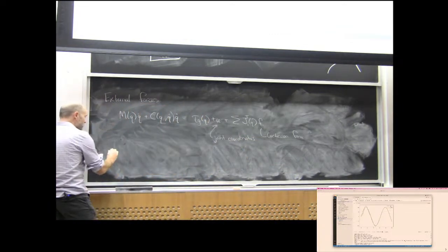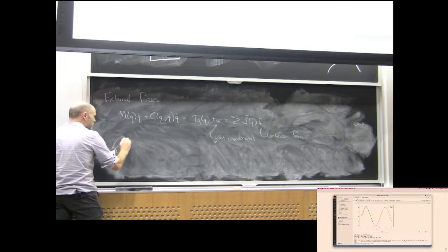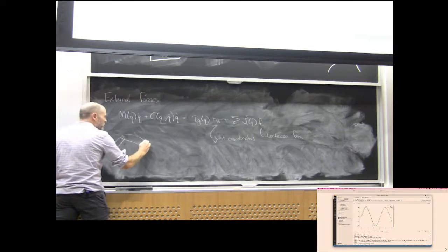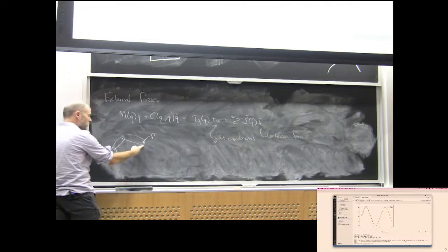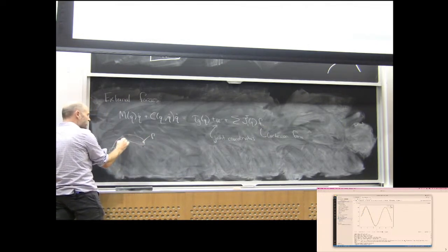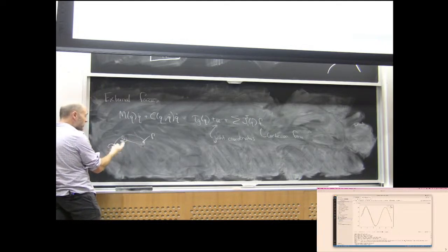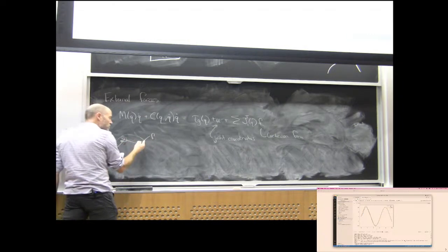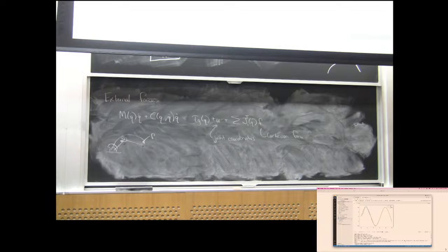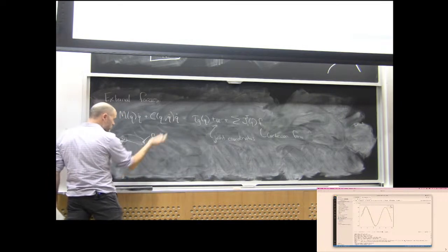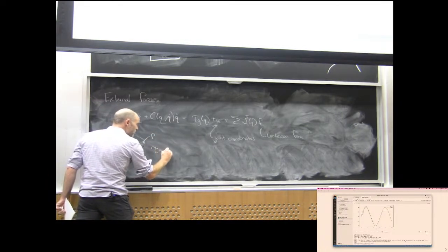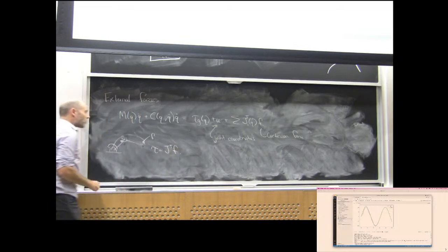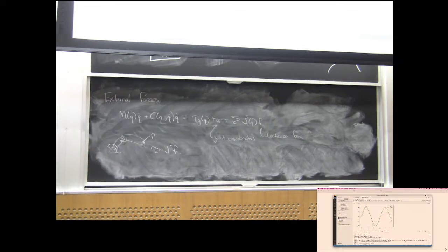If you have a robot with some joints and some equations of motion, and you apply a Cartesian force here, then the question is, how does it affect torques at the links? Or vice versa, if I were to apply torques at the links, what sort of force would I be applying at a point on the world? And the relationship here, which is there, but more generally, is that torque is a Jacobian transpose times force. And that's the one I want you to remember.